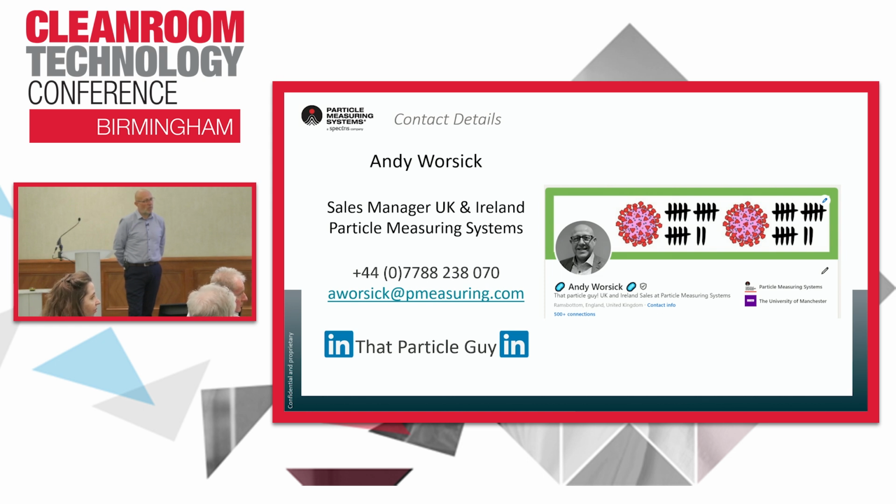But we're always compromised, because ideally we'd like to put the isokinetic sample directly in line with the open container, but we can't do that. So we go as close as we can without disturbing that air flow. So it's a reasonable representation.